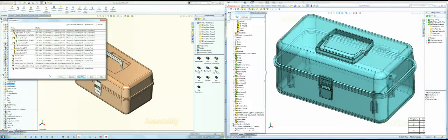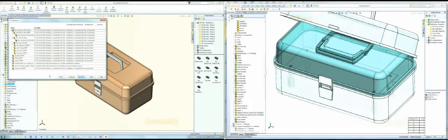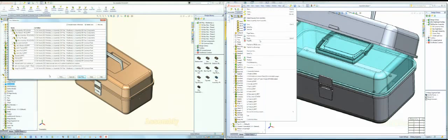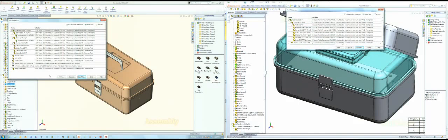Okay, you show them file, find references? Oh, yeah. Okay, the last thing we have to do is just break all the references on my side. But just to show something interesting here, if you do file, find references, it tells you where all the files are that your assembly's looking at.